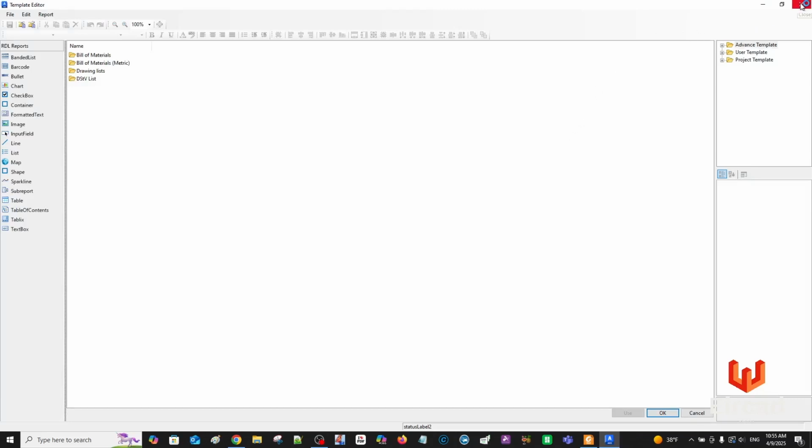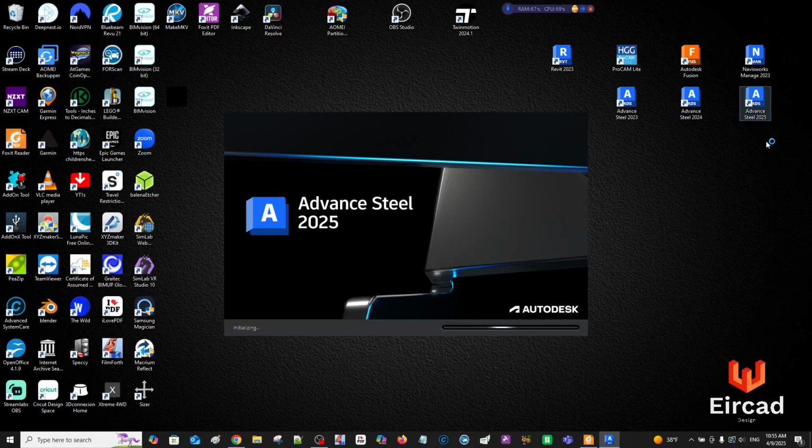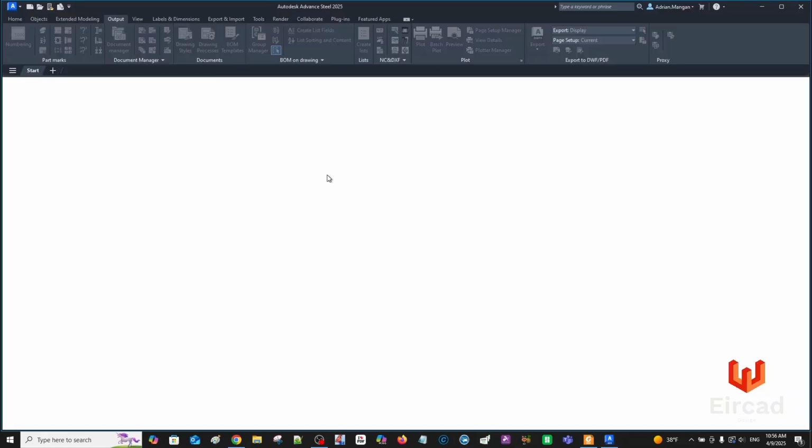And I guess the second bill of materials was open because it's right there. And let's open that again. So that was 2025. Now we'll go into the management tools and we'll do some settings. These are things I got from, I think, David Naylor, who did a document years ago. And it was useful and I took some notes of it. So like stuff like setting up your hole size, the default diameter for standard holes and stuff like that.